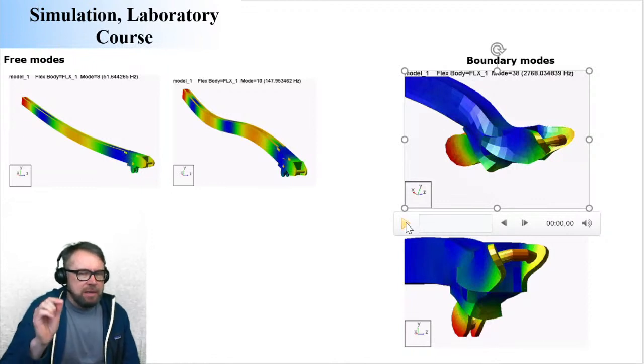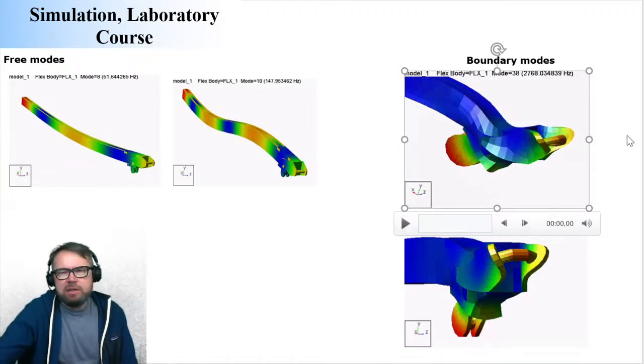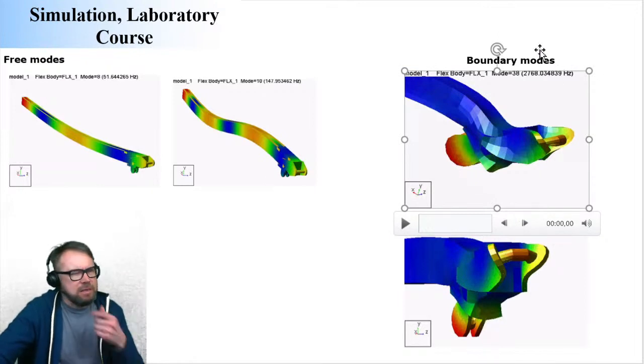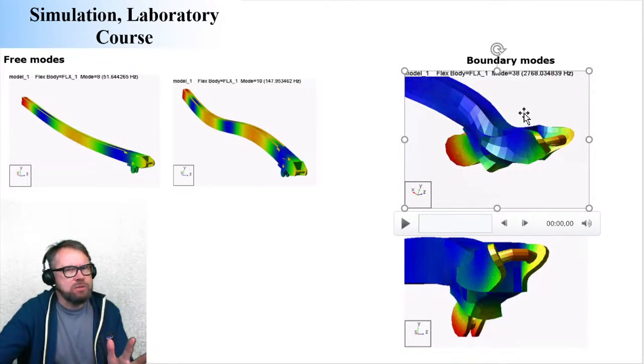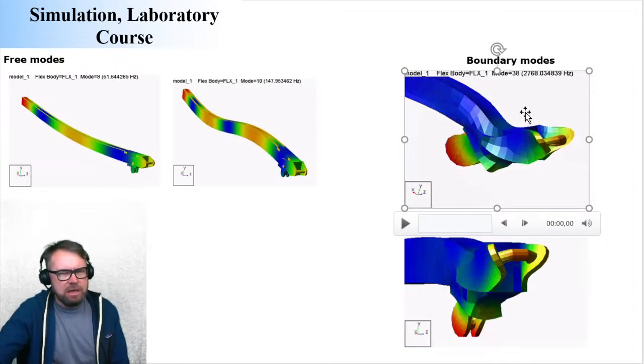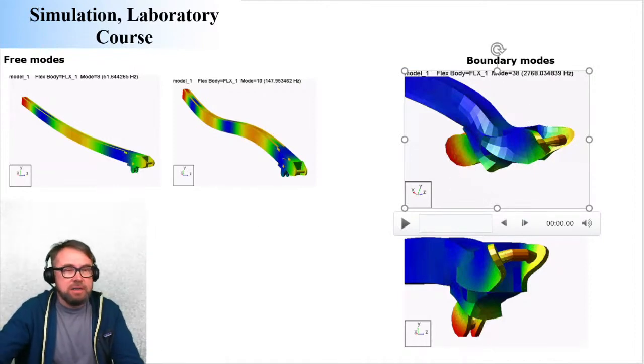You can use some tricks with these modes. One trick is to introduce very heavy damping associated with the high frequencies, it could be critical damping. That means the system can deform this way, but it cannot vibrate in this way. That helps with the time integration scheme. Still, this is good to keep in mind, and you would like to avoid this stiff system as much as you can. All right, now I'm going back to this one here.